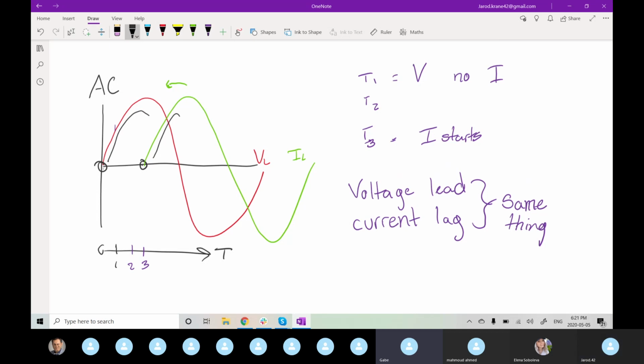And so what the motor controller designers do is, within the motor controller, they put a lot of capacitors. And those capacitors act to cancel out the inductance from the wires in your system, and make sure that the voltage is stable and protected from those voltage spikes that the inductance in the wires created.